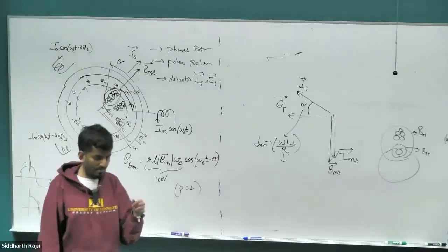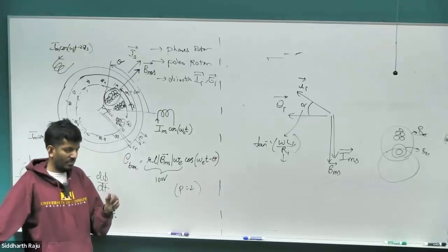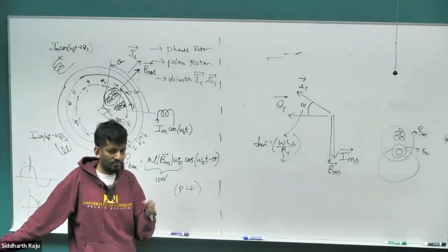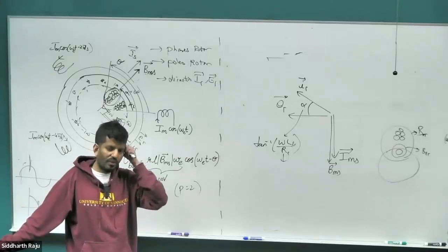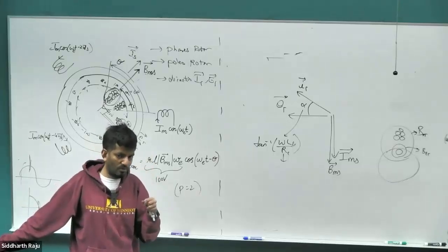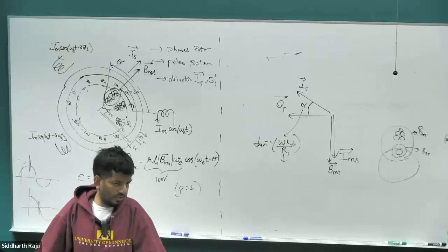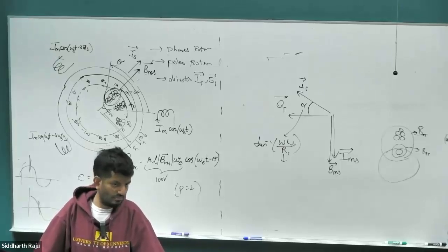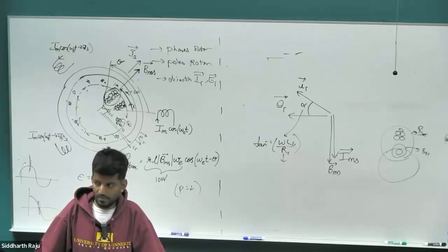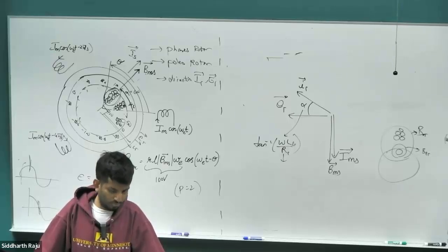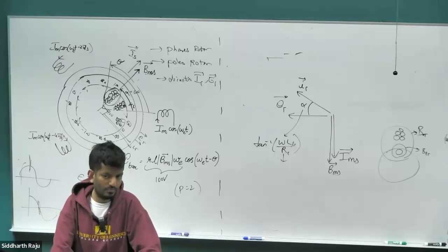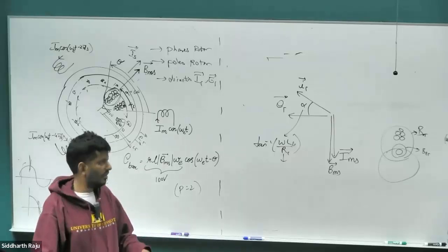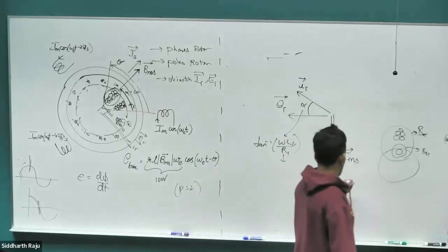Let's go back to the case of the permanent magnet synchronous motor again. In the case of the permanent magnet synchronous motor, what was the source of the back EMF? There are two contributions to the back EMF, and you didn't calculate both of those contributions in the homework, last question. What were the two things contributing to the back EMF in the permanent magnet synchronous motor? Anybody? The rotor spinning, one of them, and the other one? The inductance of the stator electromagnet.